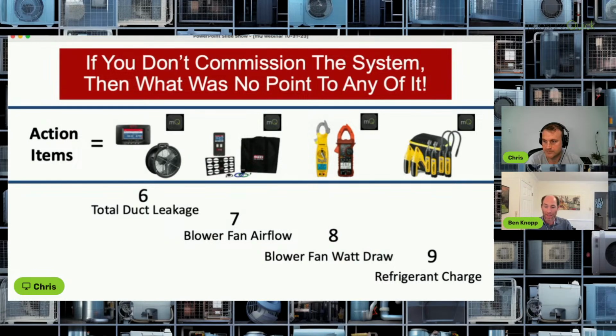So in this case, we picked an ERV and we said, okay, what's that going to do to our moisture load? And what it did was take 4 gallons of water out of the ventilation air every day on a peak dew point day. That's very significant. That was helpful in allowing us to be comfortably within the 2-ton capacity range for that heat pump, even though the Manual J didn't show it as clearly as it appears when you run the calculations yourself.